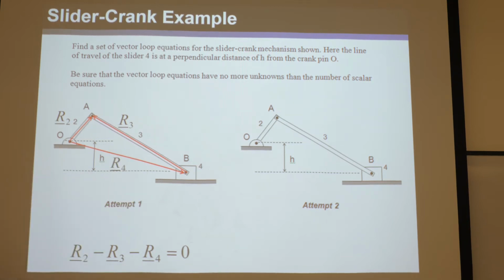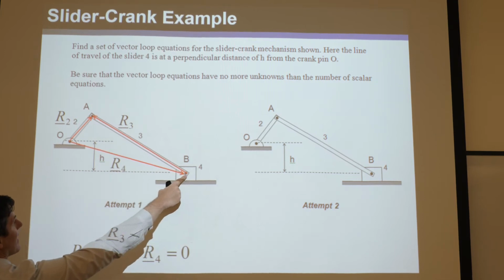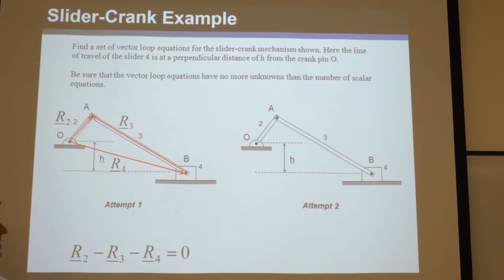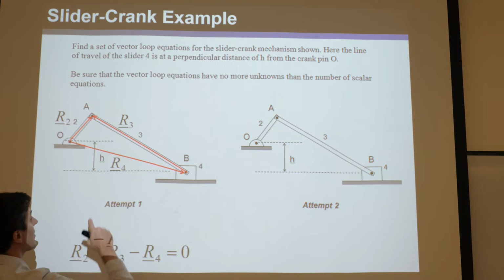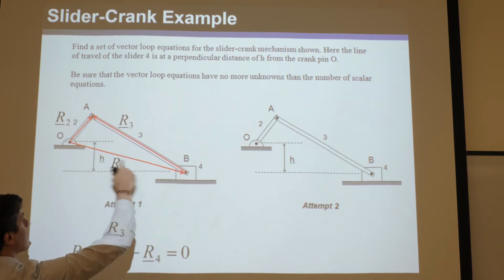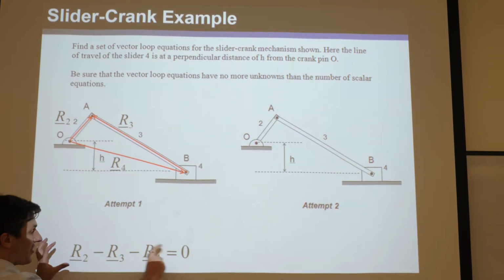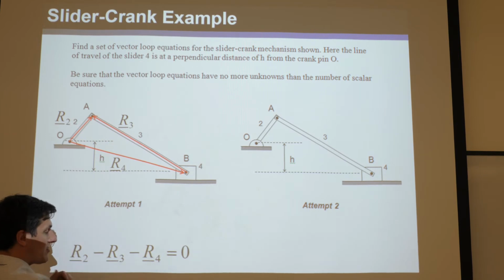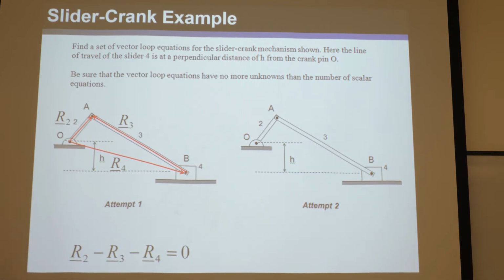just arbitrarily, okay? And so we walk, since this is tail to head, we make this plus. Since this is head to tail, we make this negative. Since this is head to tail, going back, we make this negative. Okay, and you could see we could go the other way, or we could start there and walk this way. And no matter what, as long as we follow that convention with the signs, this will always equal 0. And you should, again, prove that to yourself.